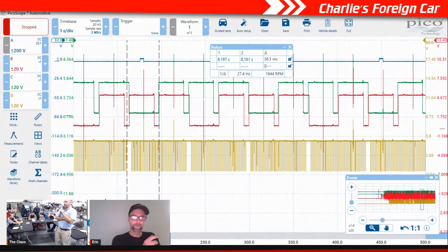On the VVT solenoid, only on the intake camshaft. Okay. And when that funky B plus grounded, it went down to 690 millivolts, and you heard the engine die down a tiny bit, and we knew it was working.